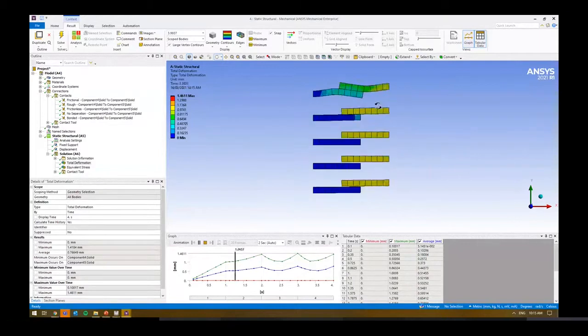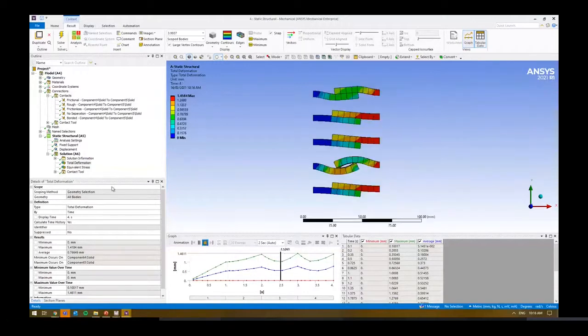So we've got bonded at the top. We've got, the second one, which is no separation. We've then got frictionless over here. So again, we're at the slide, there's frictional sliding. The rough here, right, it's able to come back, but because there's no sliding involved, when it comes back, it starts to arc. And we've got some frictional sliding, at the bottom as well, right?